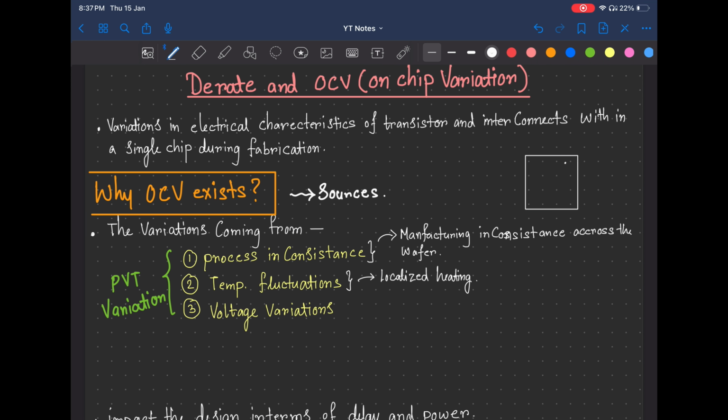At that time, 0 to 1 and 1 to 0 transitions will happen very frequently, so that part of the chip can create a hotspot, making those transistors usually slower than transistors in a dormant block nearby. So obviously temperature fluctuation can happen.